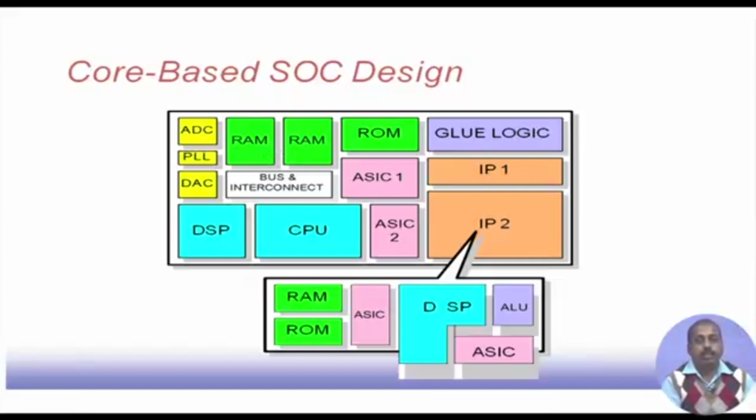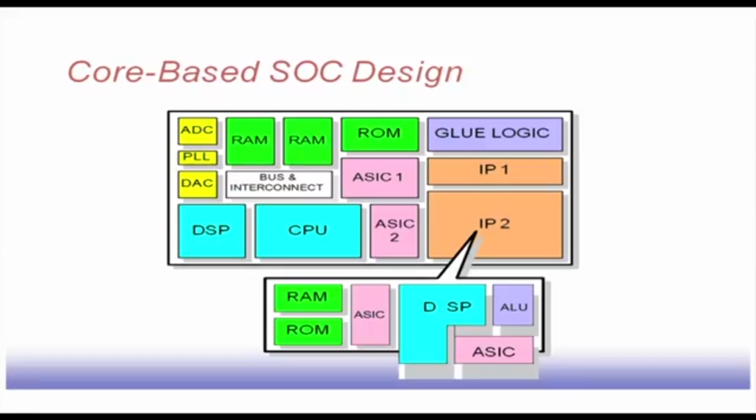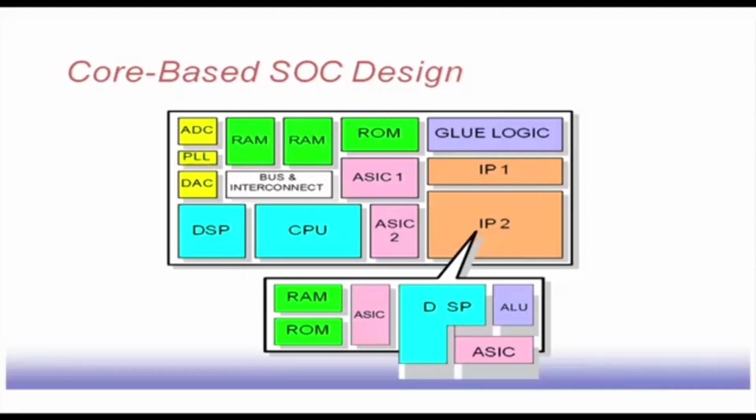Now if we want to design such a system, we have to take different components from different vendors, mount them on a PCB and make connections between them. The disadvantage is that the CPU to memory communication is going to be off chip communication, and we know that off chip communication is much slower compared to on chip communication. Since off chip communication is slow, one possible solution is to have the CPU and memory on the same chip, but one system designer's requirement is different from another designer's.